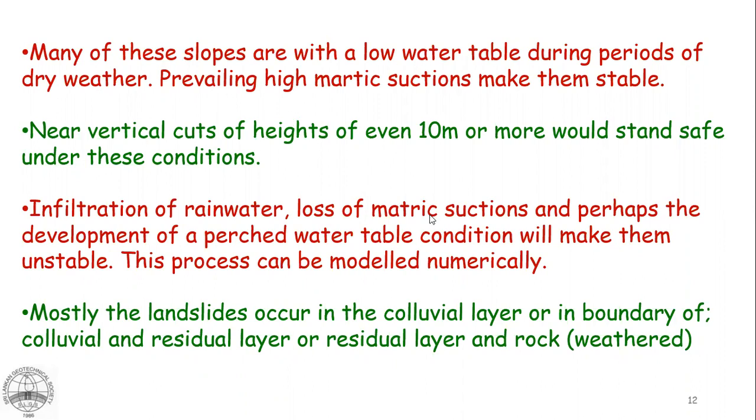Infiltration of rainwater, loss of matric suction, and the development of perched water table conditions would occur with rainfall and make the slopes unstable. This process can be modeled numerically. We have done that in a number of research projects.